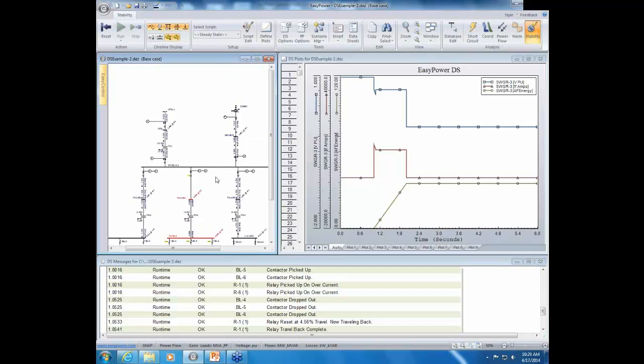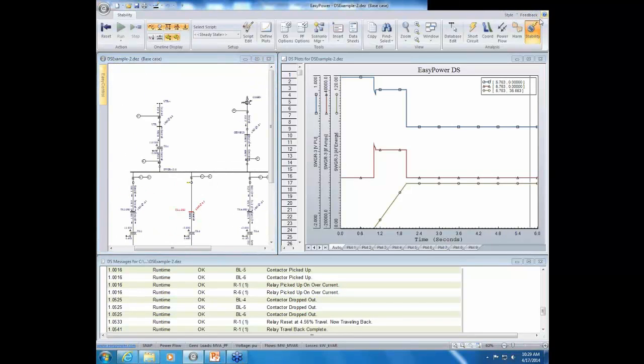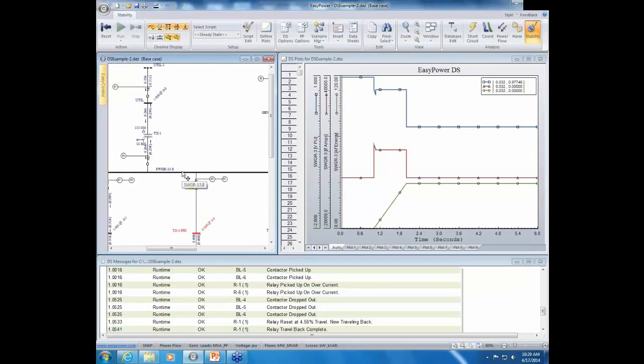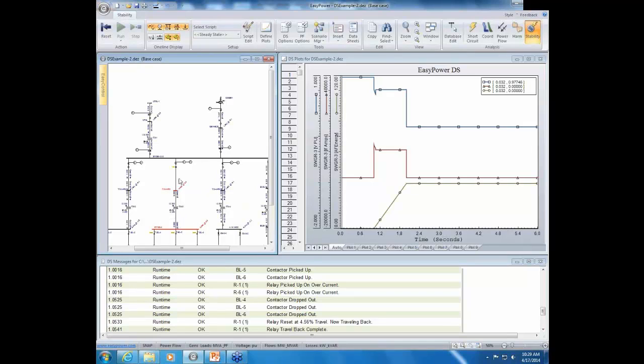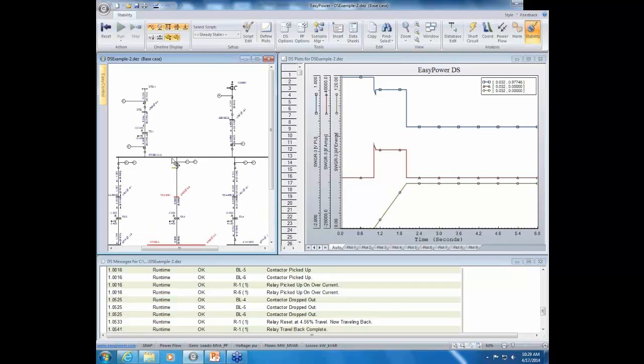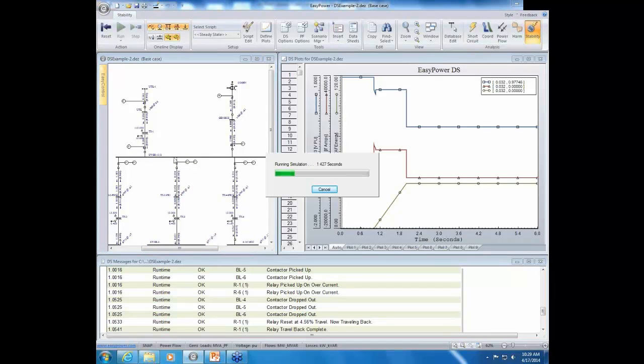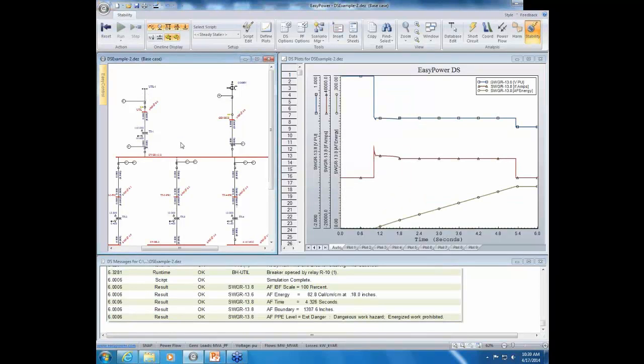The next example that I want to show is within the switchgear 13.8 bus. The first case that we had was just a radial system. We expected this relay to trip for a fault at switchgear 3. Now, when we get into switchgear 13.8, and I'm going to fault this, it takes a little bit of time to run this calculation. We have multiple sources that are supplying power. Therefore, to shut off both sources, multiple relays will need to be tripped. Their connecting breakers need to be opened, and then the source, the energy is accumulated.